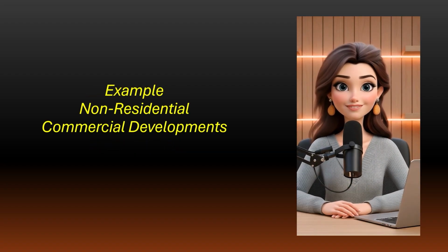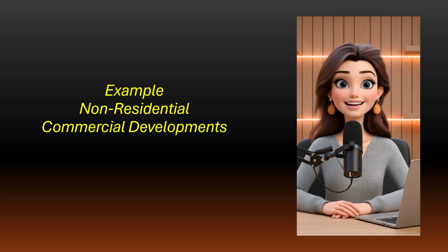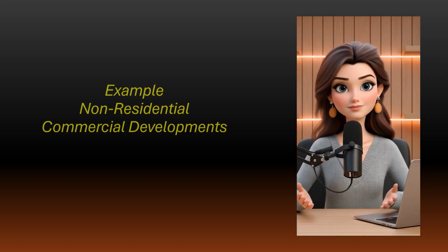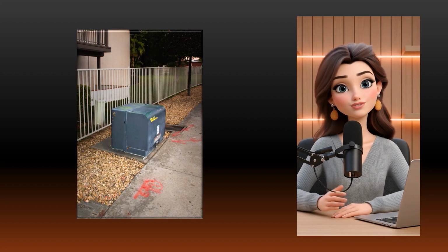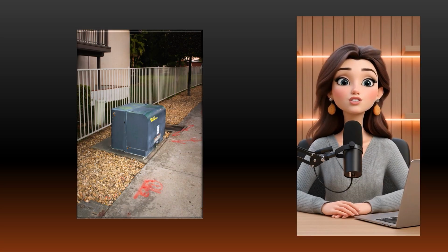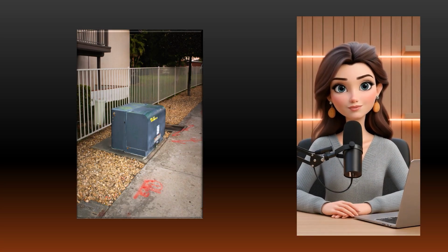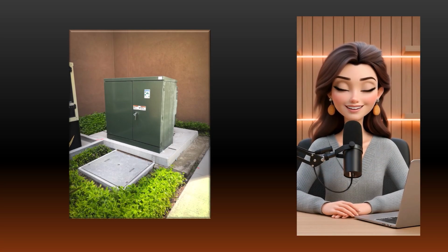The most significant difference between a residential and non-residential project is the size of the electrical load utilized by the applicant's facility. In Part 2, we discussed how up to 20 homes can be served by an electric transformer like the one shown at the left. Since commercial or industrial developments have much larger electric loads that can be hundreds of times more than residential projects, they typically require much larger transformers.